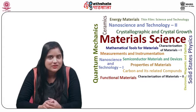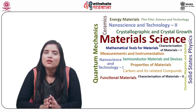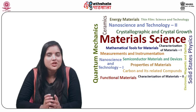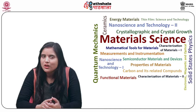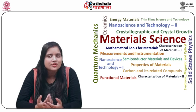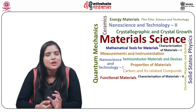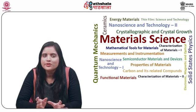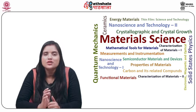Let us now discuss the various factors that affect the milling performance. Factors affecting the milling performance include mill geometry, ratio of angular velocities of the planetary to the system wheel, temperature, grinding atmosphere, chemical composition of powder mixtures, chemistry of grinding tools, etc.